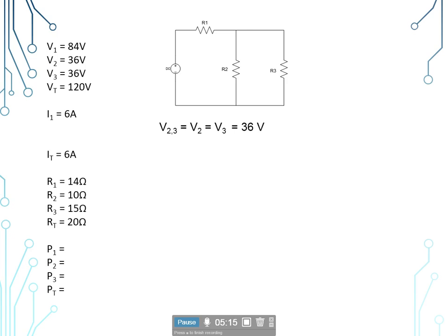Now, this being said, we need to make note and keep in your memory that if either one of those parallel branches has a series string in it, we have to redraw our circuit a couple more times. We would have to combine those two into one load before we could do the reciprocal formula of it. So keep that in mind if you get one like that.